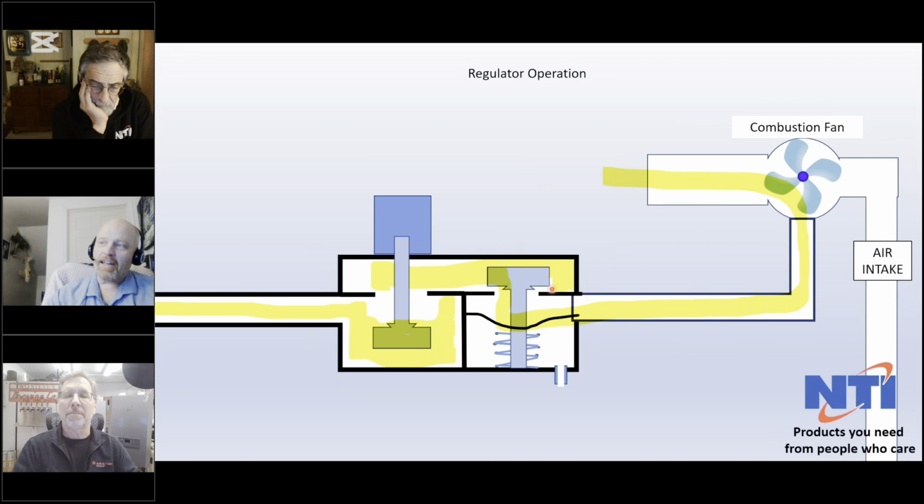He says, "Well, we used a low profile vent and they extended the intake too far. And it was up against the flat plate. And when I sealed all those holes, the boiler wouldn't fire because of the sealed combustion," which of course they were rewarded. But I guess the question always arises: what happens when those gaskets, 15 years down the road, are breaking down, allowing air seepage through them? What's going to happen to combustion?